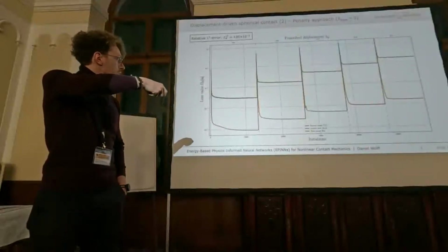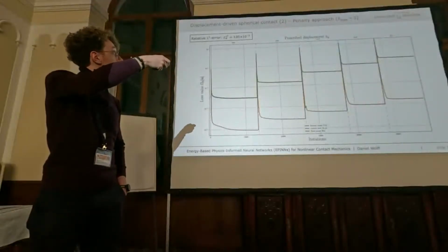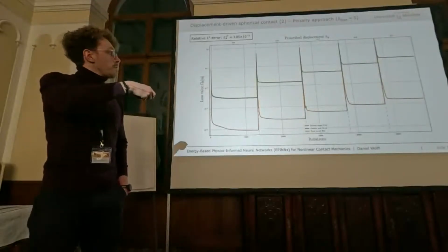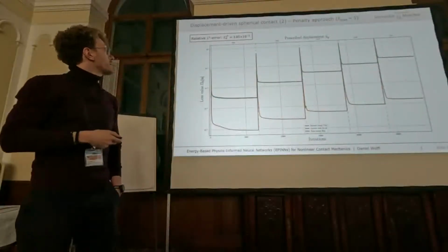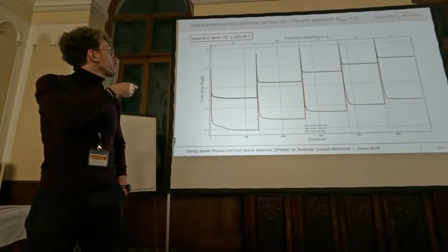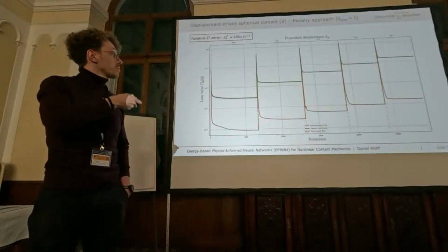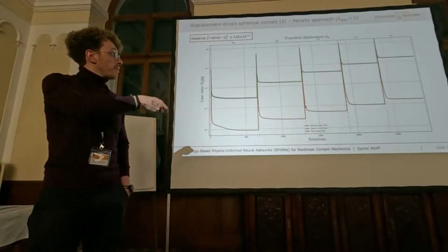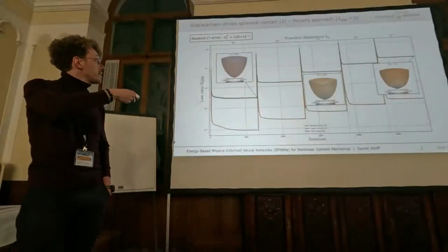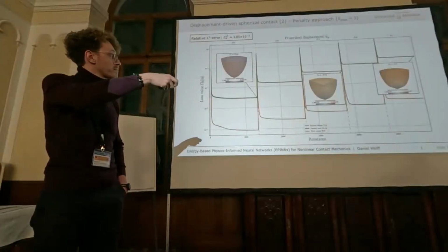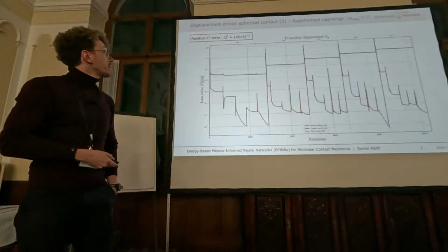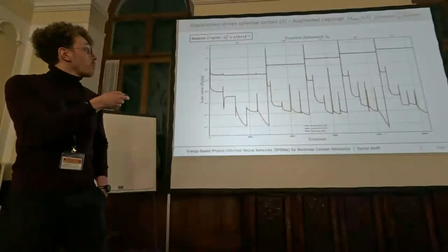And in orange, you see the contact potential, so this penalty potential. Basically, we already get a quite decent L2 error of 3.8 times 10 to the power of -3 in the final load step compared to the FEM solution. And because we reconstruct this nonlinear load path, we get the solutions along it. We can now compare this to the augmented Lagrange version.